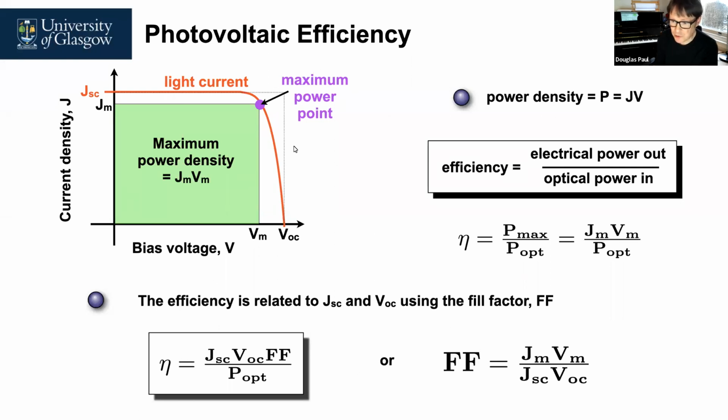And as you'll see, if you look up any papers on photovoltaics, what is normally defined is the standard test conditions at AM 1.5. We'll talk about that in a few slides. Then you're given the short circuit current density, the open circuit voltage, and the fill factor of the cell. From all of those, you can compare how well these cells will work under different loads and different power conditions.